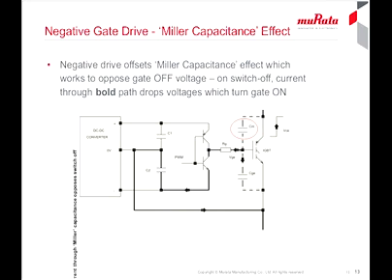Kelvin connections at the emitter of a device like an IGBT do not help stop the effect of Miller capacitance producing transients. What happens is that when a power device turns off, its collector goes positive. This produces a pulse of current through the device's internal capacitance Cm, marked here with a red circle, from collector to gate.